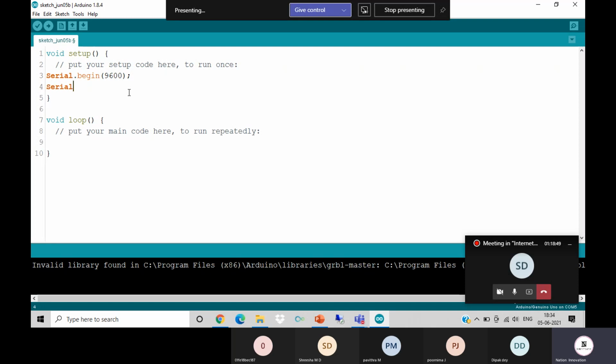For that, we require this small command, Serial.println. The ln is for writing into the next line. When we go through the next works, we will be revising these things again. Let's write hello in the setup, and then in the void loop section, let's print Serial.println world.